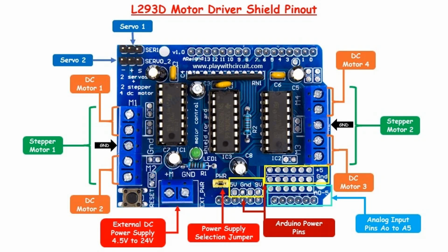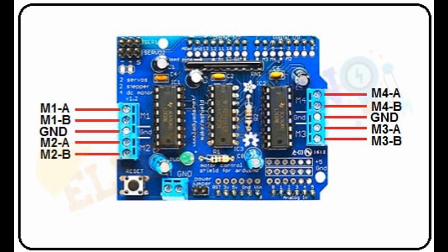5. Brushless DC, BLDC, servo drivers. Function: BLDC servo drivers control brushless DC motors used in servo applications. These drivers control the motor using feedback from Hall sensors or encoders to ensure accurate position and speed control. Operation: BLDC servo drivers use a 3-phase inverter to supply the motor with controlled power. The feedback loop continuously adjusts the motor's rotation, ensuring smooth operation and minimizing loss.